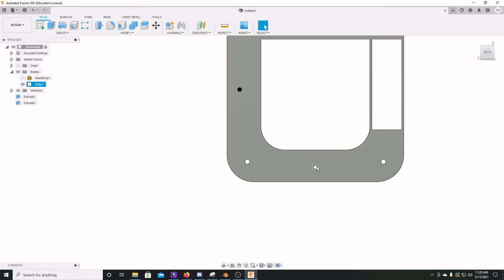Okay, so now we know where to start. We're going to have a little bracket, a Z-shaped bracket, attached to the screw, and that's going to have the spring and a magnet attached to it. This Z-shaped, the top of the Z-shaped bracket is going to be 12 millimeters in height. So let's sketch that out here.